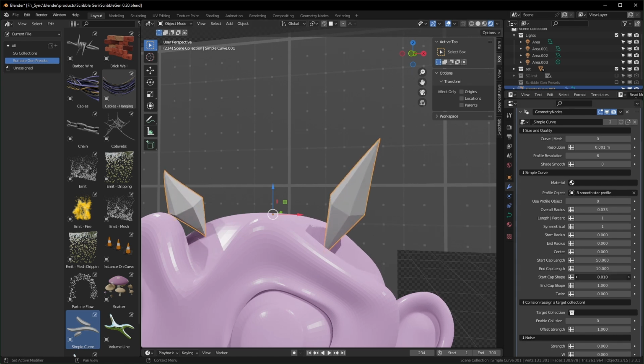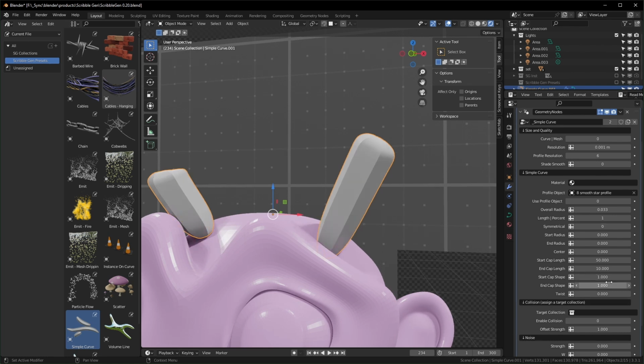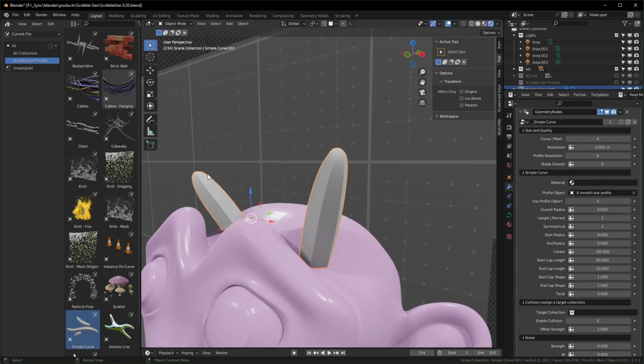And if you have this not symmetrical, let's turn this off, asymmetrical, you'll be able to change these individually like that. Usually what I like to do, it's just a lot faster, I set it to %, push the center just one direction like this. So I'll set it to -50 like that. And now it's completely flat at one end.